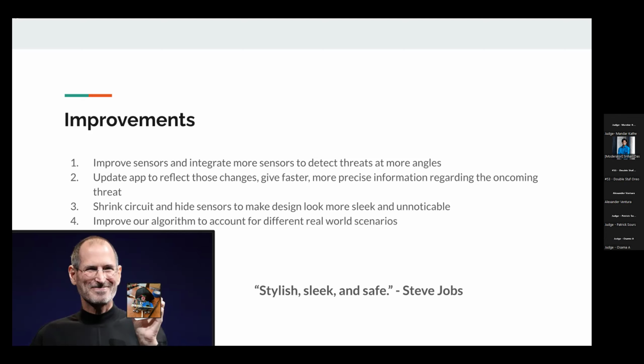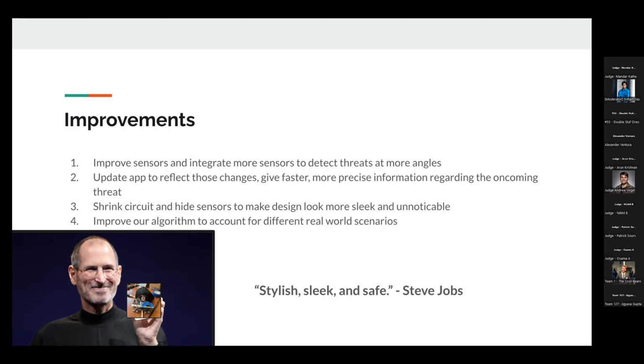Thank you. I guess a follow-up question to that. A really cool idea. Have you thought about, based on the signals that you receive, if there's a false alarm, training based on that to improve your sensing technology? The algorithm on the Arduino will calculate the average of many sensor pulses. It's not just going to fire if a fly flies in front of the ultrasonic sensor. It has to be a consistent object that's nearby after a period of long distance range of empty space. So only if there's an object that's consistently nearby that person after a period of open space will it actually signal the Arduino to fire.